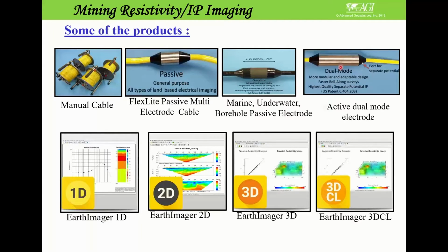These two options are mainly used for any resistivity studies and resistivity IP studies, and especially IP studies on this dual mode. Because most of the time people prefer to use non-polarized electrodes to get the cleanest signal, and especially chargeability, the cleanest chargeabilities in the non-polarized electrodes through these connections.